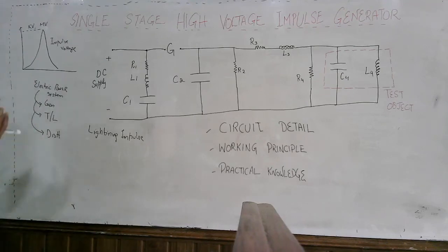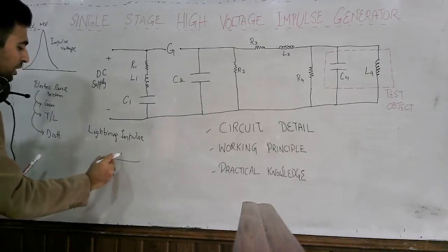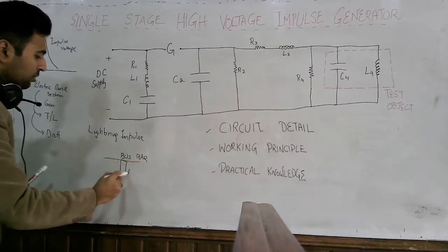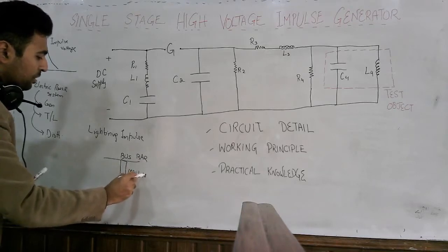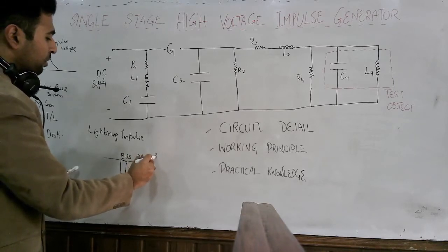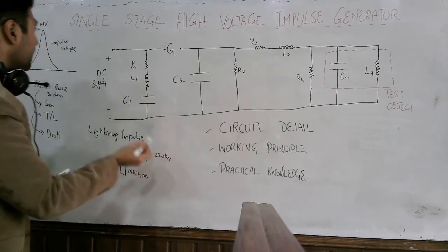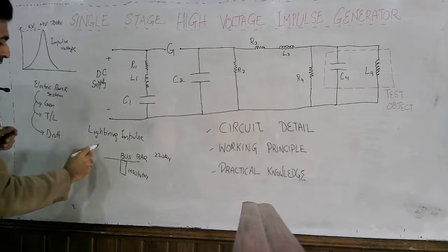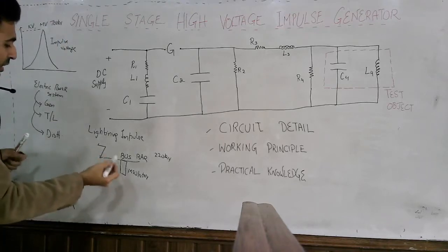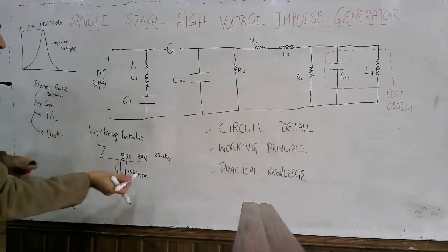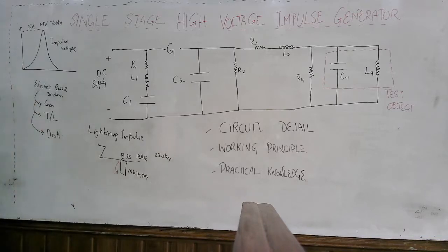It is dangerous for the electric power systems. If you have a bus bar, the bus bar is supported on insulators. Similarly, conductors are also supported on insulators. Now, the bus bar is intended to operate, let's say, on 220 kilovolts, but if there is a high voltage impulse of around 700 kilovolts from a lightning strike somewhere on the bus bar, then the high voltage will also appear across this insulator. So this insulator may be damaged as a result of this high voltage impulse.